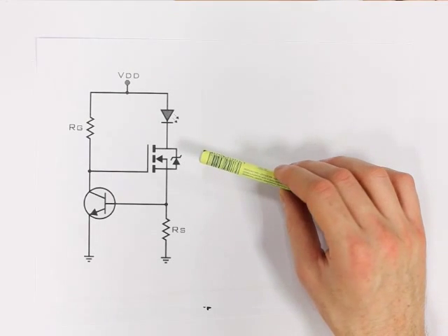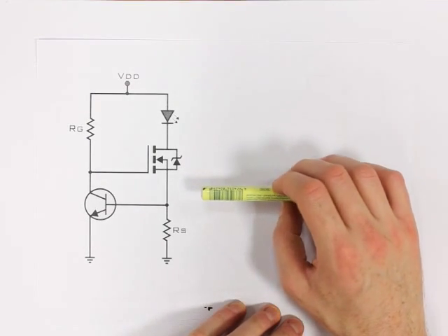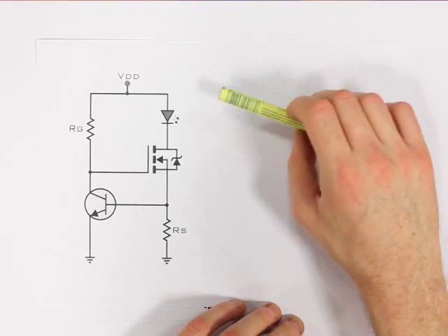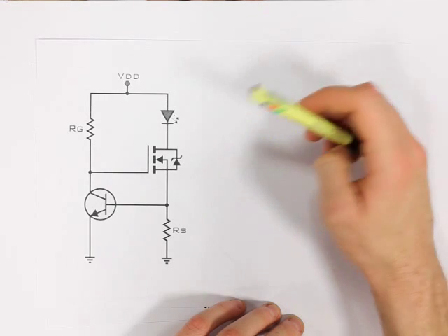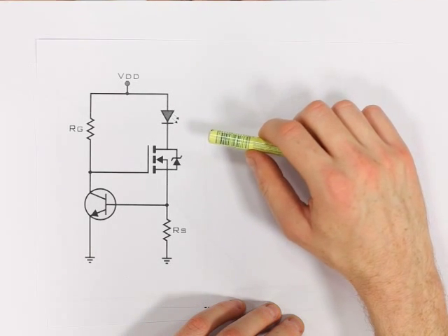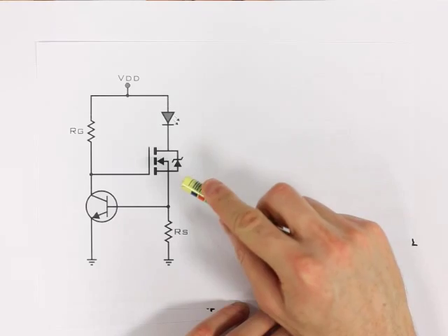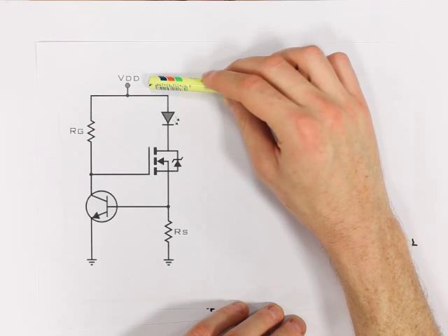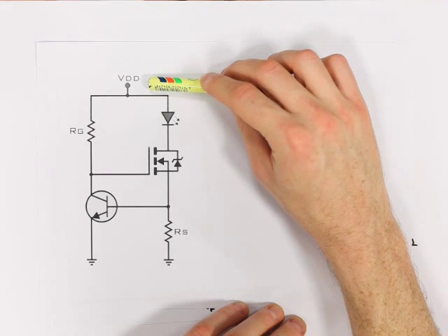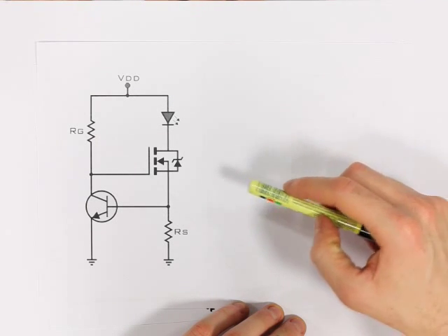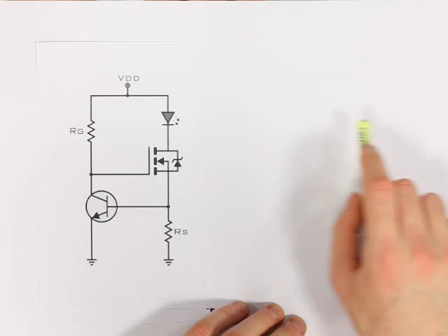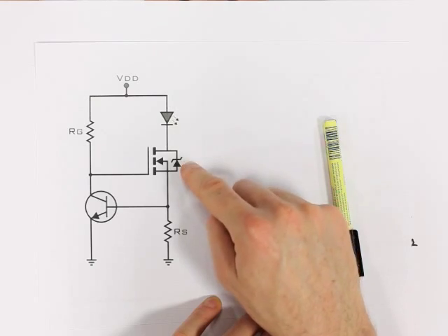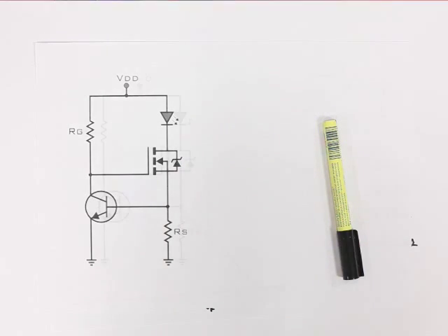And yes, the efficiency there is really just the ratio of the LED forward voltage to the supply voltage. So we've got the same efficiency here of about 2/3. However, as we saw, this circuit has the very big advantage of being able to cope with variations in our input voltage. So the circuit's more complicated, it doesn't save us any power, but it is very useful for making sure that our LED gets the correct current for a large range of supply voltages.